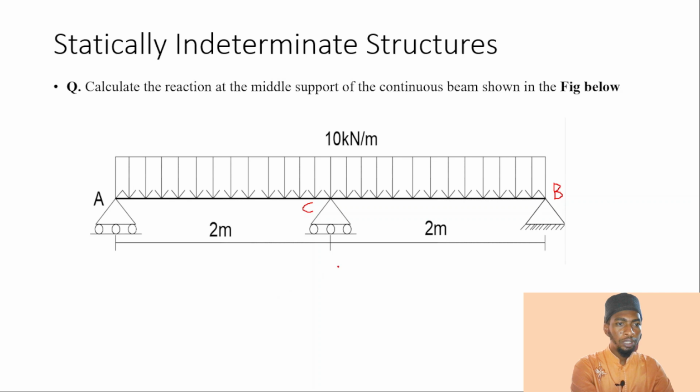So we know that normal reactions are 3 in beams, and let's confirm here, is this 3 or is it more than 3. So we have one here. This is also a roller, we have one unknown. This is a pin support, we have one horizontal and one vertical. So we have two.